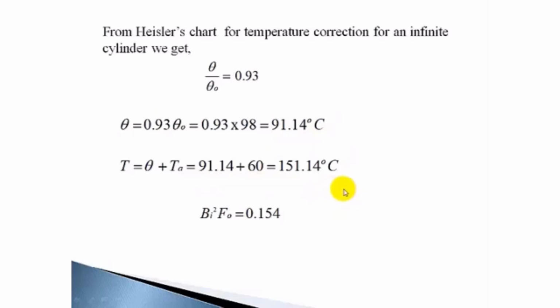And you can observe that the surface temperature is going to be less than these temperatures. So the axis will be hot, and as you move on to the surface, the temperature will decrease, because convection is not happening at a faster rate. Temperature is not attaining uniformity within the body. There is a variation of temperature from the axis to the surface. That's why we cannot use lumped heat analysis. There is a lot of variation of temperature, and temperature variation with respect to position we cannot neglect. So we have gone for one-dimensional analysis, and the Heisler chart will give the solution in a graphical form.